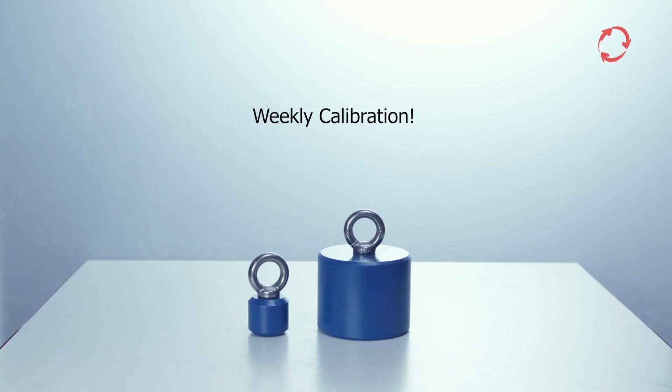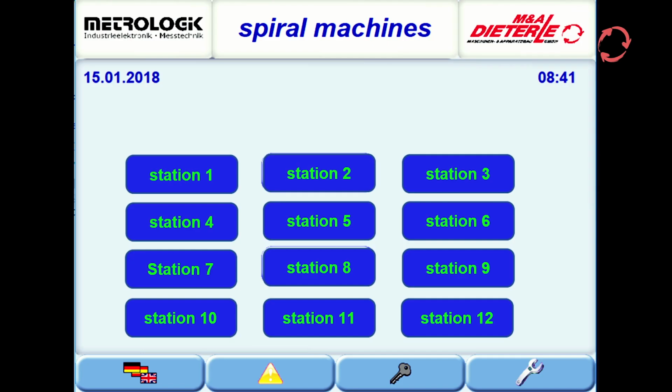One small and one large calibrating weight, approximately 500 grams and 5,000 grams, with a hook at the top, are needed for calibrating the thread tension sensors. The 500 gram weight is for calibrating the 10 Newton sensors, and the 5,000 gram weight is for the 60 Newton sensors. The Spiralmachine's selection window can be found above the service button located at the bottom of the touchscreen.